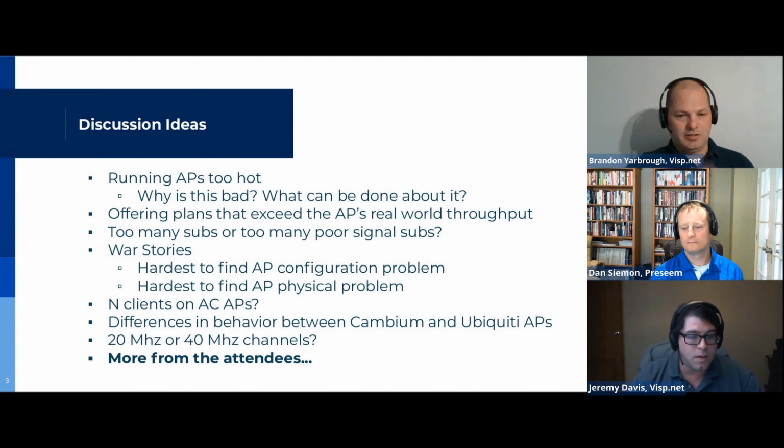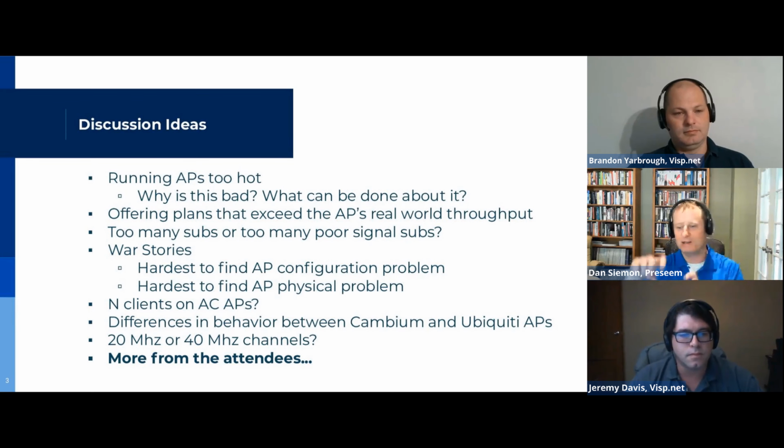Yeah, that's a great analogy, Jeremy, as far as the piece of the pie puzzle. Especially if you're talking about base cells in an LTE system, you get 1 or 2 people with a really bad SINR or bad signal, it really can wreak havoc on the entire access point. And the thing we're talking about there with the pie, I kind of think of that as airtime, right? You're dividing up how much time the access point gives to each subscriber. And if you have a lower modulation, that person's going to take a bigger chunk of the pie. That's kind of what you're saying?